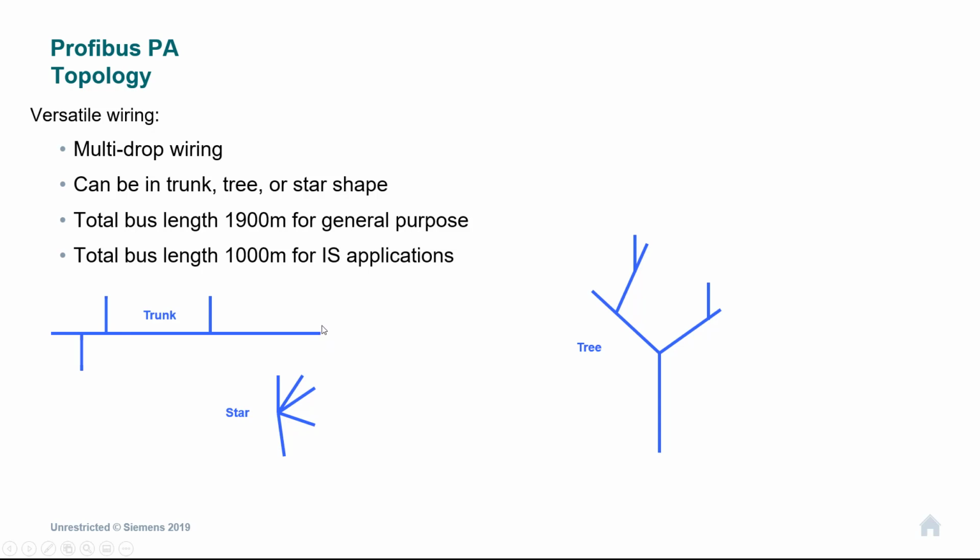At the end of this cable you would have an end-of-line terminator, so just one, and then we would have spurs going off to your instruments. You don't need to terminate at your instruments, you just need one end-of-line terminator at the end of the trunk. That keeps your network nice and tidy. You're only taking one cable around, say, your tank farm and dropping your spurs off.